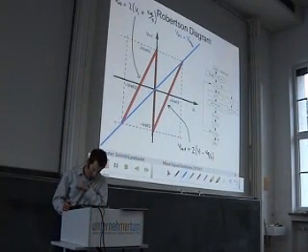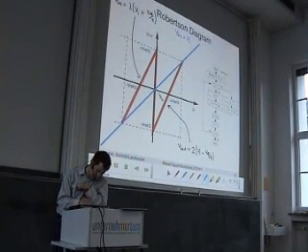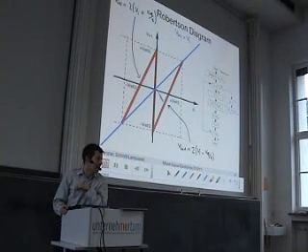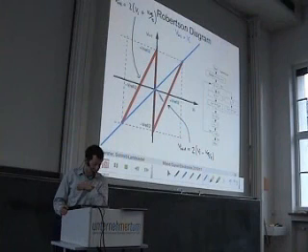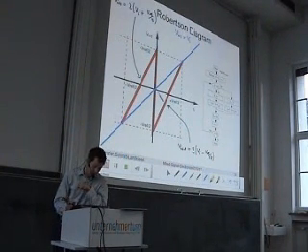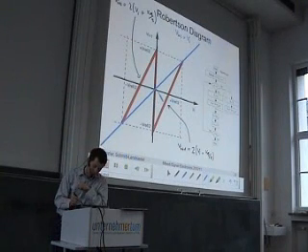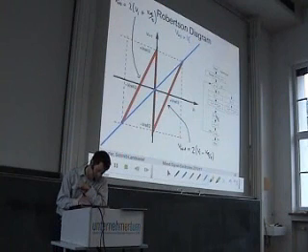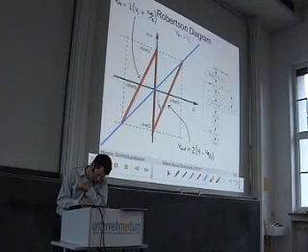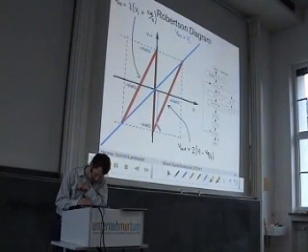So let us start with an input voltage that is, for instance, here. So this is our Vin. We sample this and then we go into the algorithm. Well, we see that it is positive, so we have to go to this branch, and in a graphic way we say, okay, this voltage leads to this remainder.